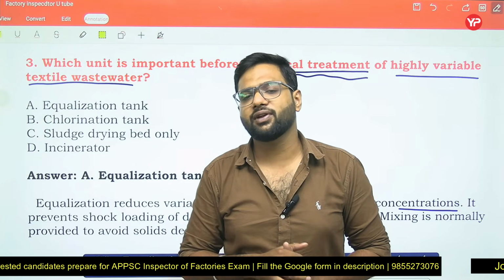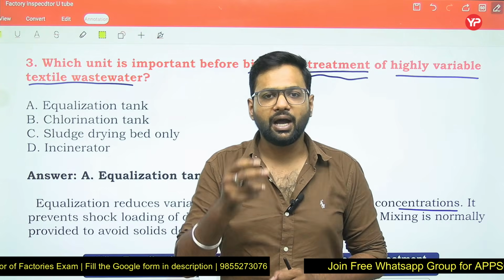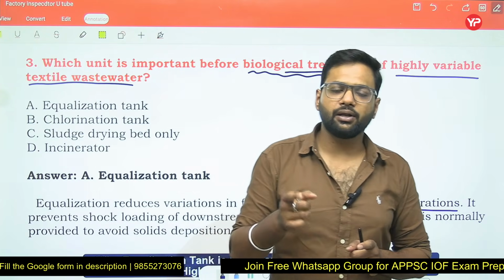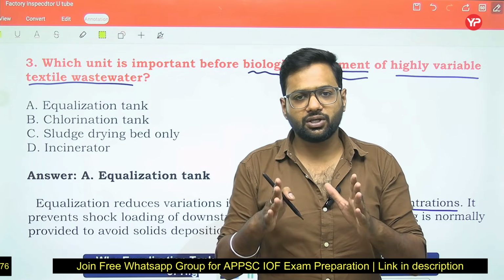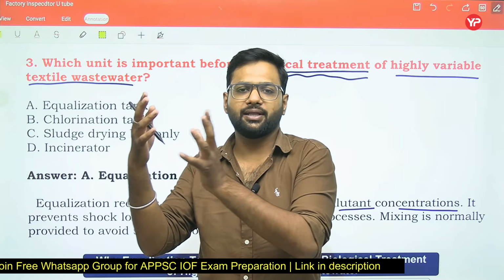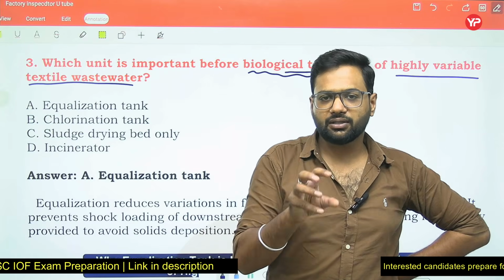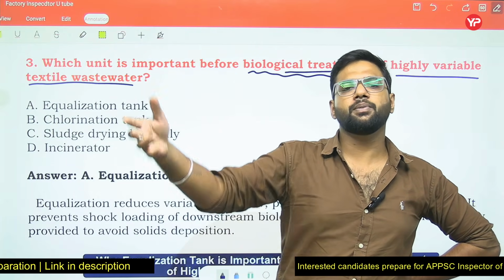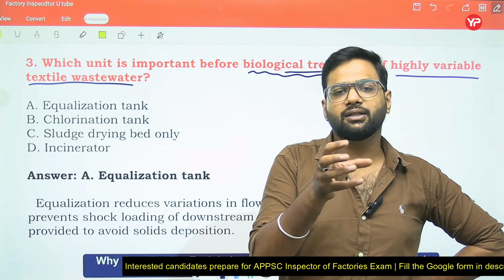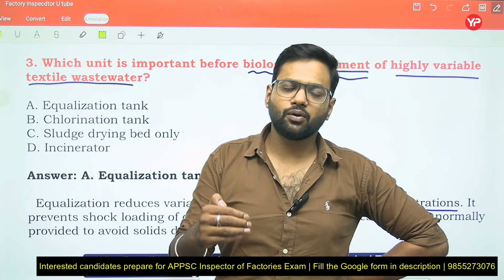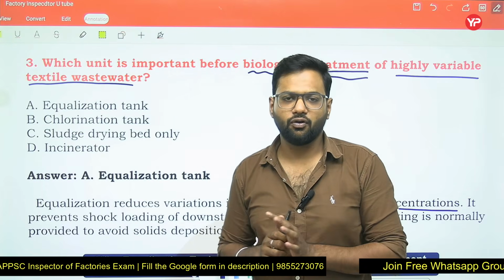So these methane formers, friends, are the microorganisms that work in the narrow pH range of 6.5 to 7.5. Ultimately, when organic matter is decomposed anaerobically, it is converted into methane. Until decomposition is completed, methane is released. When methane is not being released, that means decomposition is incomplete. The conversion of organic matter into methane happens first into acid alcohol, done by the acid formers, and then this acid alcohol is further converted into methane by the methane formers. So basically the last product formed is methane.